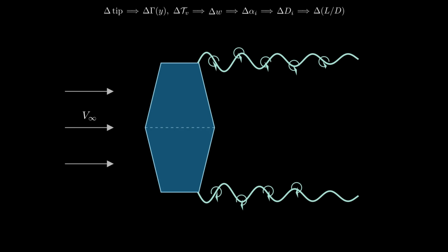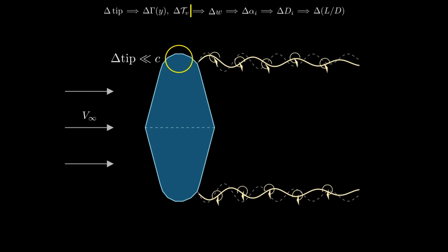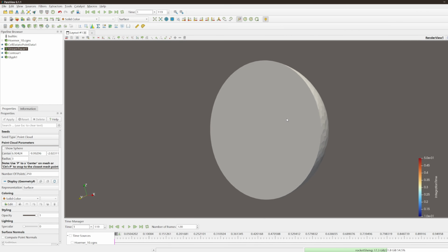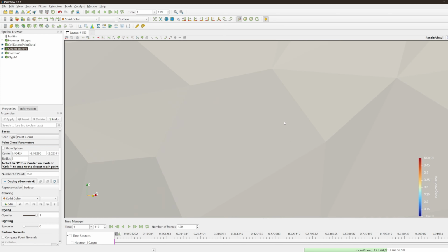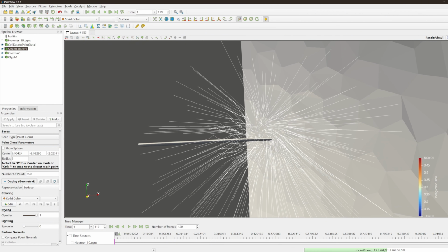Every subtle change in wingtip configuration directly alters the intensity and evolution of wingtip vortices, significantly affecting induced drag and ultimately impacting the lift-to-drag ratio of the entire wing. These seemingly insignificant changes often determine the ultimate limit of flight efficiency. In aerodynamic design, engineers have developed various wingtip configurations to effectively reduce wingtip vortices and induced drag.